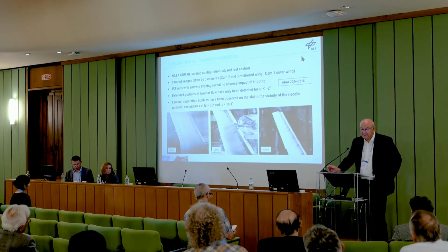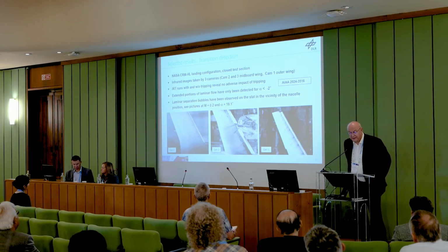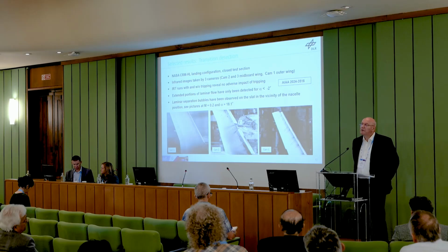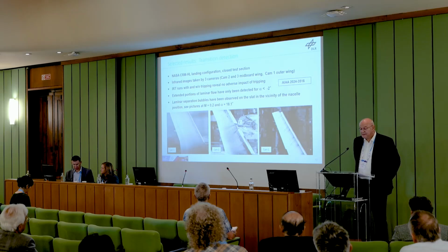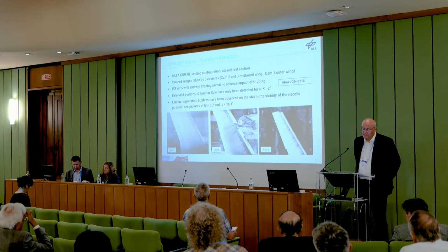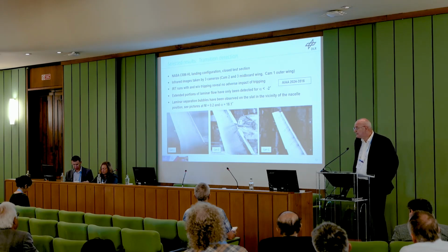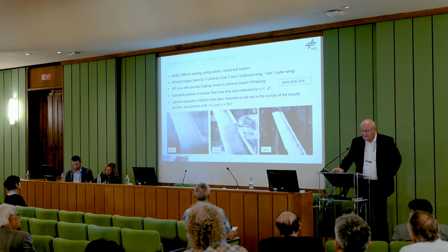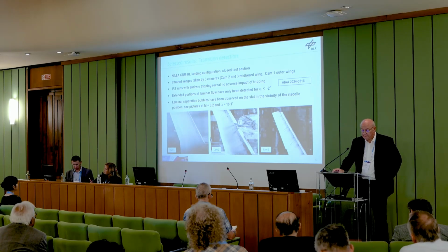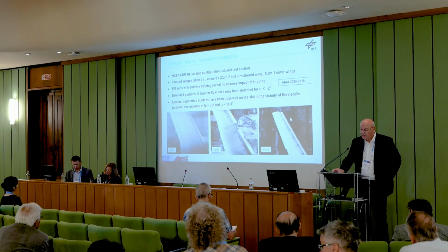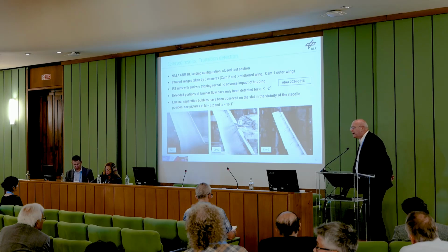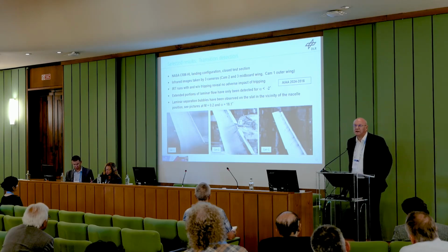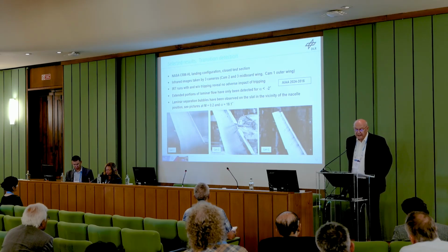Next point is the transition detection. We took infrared pictures for all configurations in the closed section, and this is an example for the NASA variant in landing configuration. We had 3 cameras, 2 looking at the midboard wing, that is cam 2 and cam 3. You might recognize the nacelle down here. And 1 cam looking at the outboard section. We are in a Reynolds range of 0.5, 0.6 million, so usually it's not too critical for laminar effects, but you want to check that. And that's what we did.